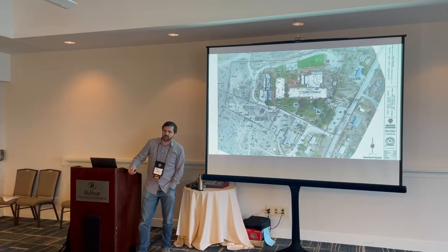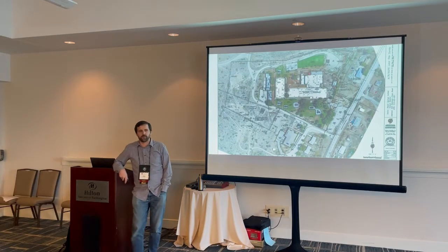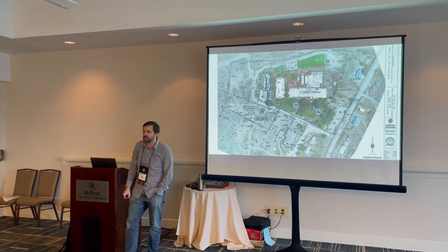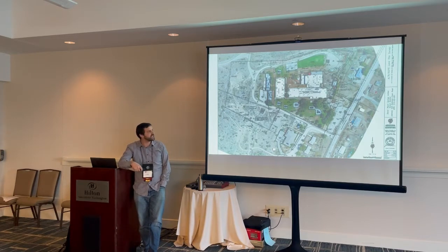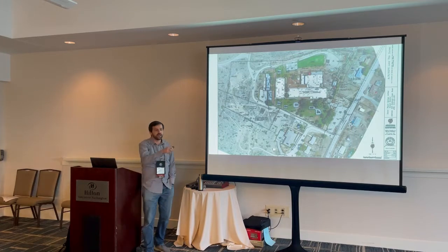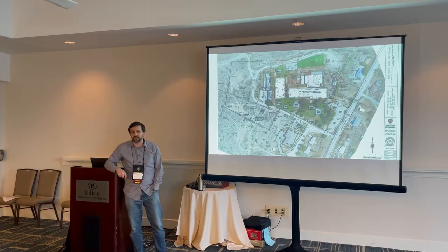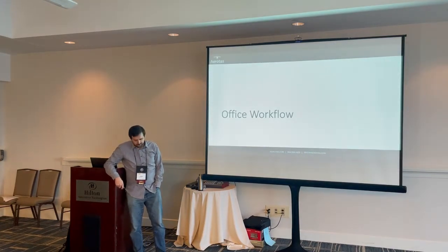That is what we are talking about today. How to go from flying the LiDAR drone, push and go, the thing buzzes around and gives you 25 gigabytes of raw data, into a survey, because there are quite a few steps that go in between flying a drone and getting to this, and that can take an awful lot of time. And we're going to try and cut that time down as much as possible.